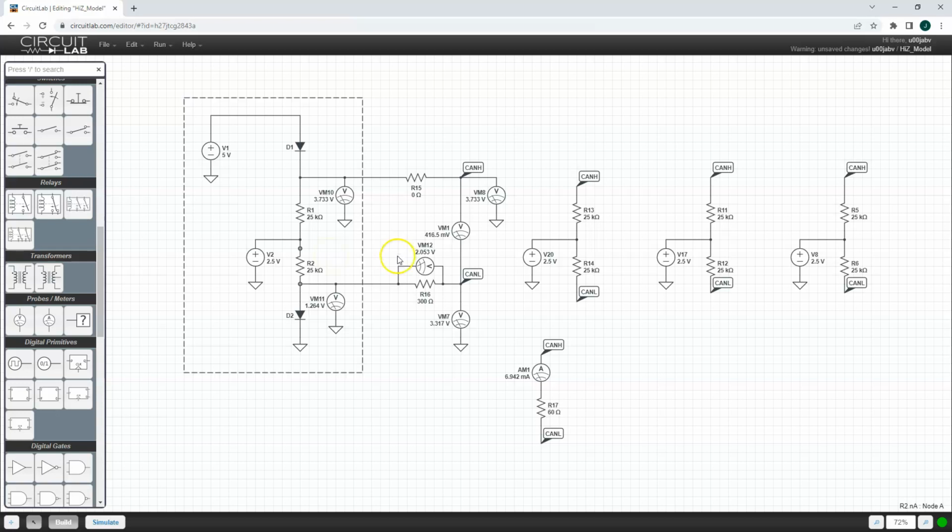And basically, I guess to simplify this, because of the series resistance, I'm dropping a voltage across this. And in so doing, this is the voltage that the CAN does not see. The other devices can't see this. So this is limiting the current that flows through termination, of course. And if I limit the current that flows through the termination, it's all about what the voltage drop across that is.